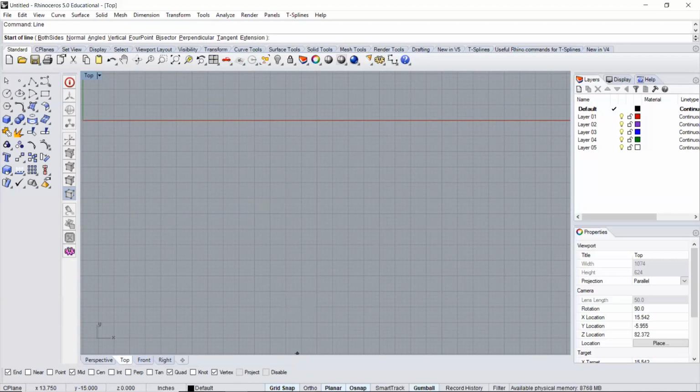Again, things like that, if you're wanting to do things more freeform, it can be helpful or hurtful. So you just want to be aware of whether or not you have them on. I tend to leave grid snap off. Ortho will lock things at 90-degree increments for me so that I can no longer move at angles other than 0 or 90. And so if you're doing very perpendicular drawings or regular geometry, that could be a really useful thing to have on.